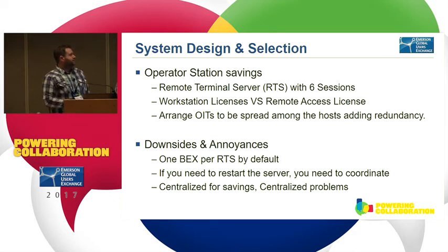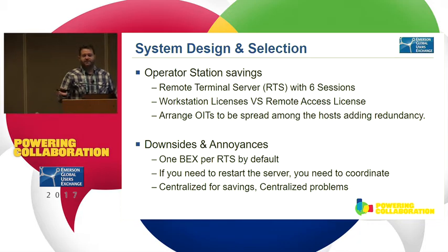We also moved, we showed you the diagram of the clusters where everything's sort of widely distributed. It's not like 1, 2, 3, 4, and all of those ones are in the same room. You want to kind of spread it out so that if you lose one terminal server, it's no big deal. You might lose 1 operator station out of the 8 in the room. But if you lose the whole server room, maybe you don't want any room in the building to lose all of their operator stations because they still have to run the process. So in general, that was also a consideration, spreading that out, redundancy, and what's the worst case scenario for losing everything and keeping going.